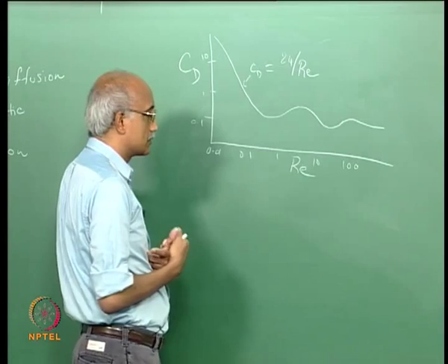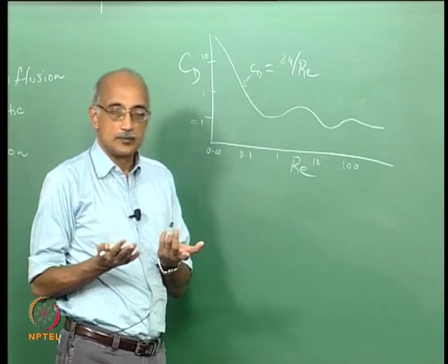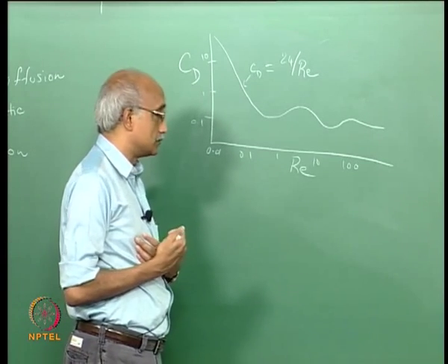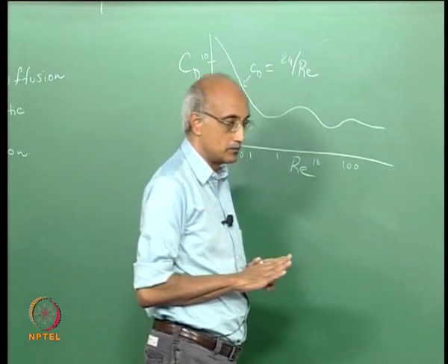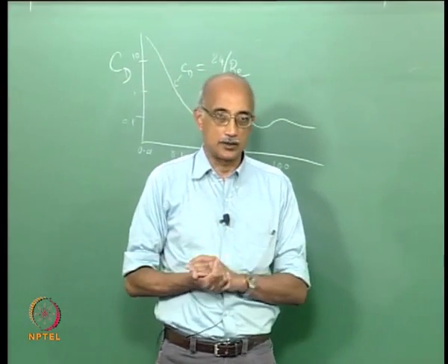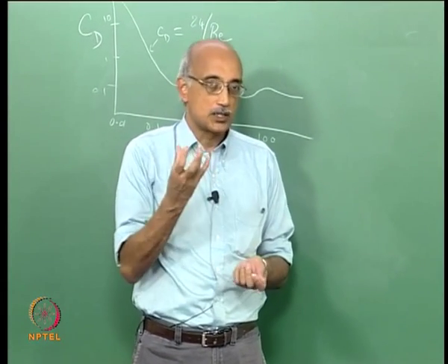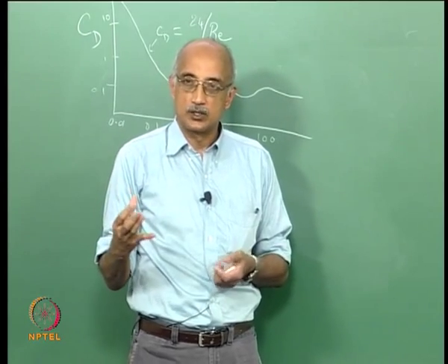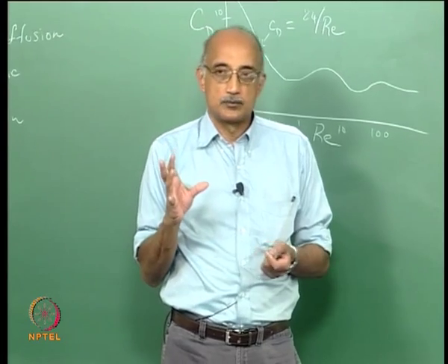Yeah, in the turbulent regime, all you can say is that fluctuations in the Reynolds number do not have a significant effect on the drag force, mainly because in the turbulent regime, the flow itself changes its character. You're essentially having a situation where parcels of fluid are being flung about in turbulent eddies. So it becomes a probabilistic process.